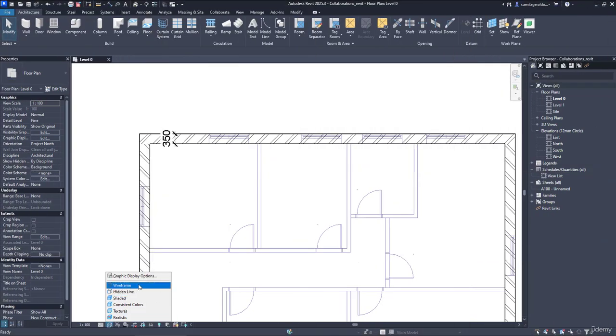Because with that, we can see where the windows and doors are located, so we can model these elements in the right places. Now, I encourage you to continue modeling the remaining elements. First, start with the interior walls by measuring the thickness with a dimension line. Then choose a type, duplicate it, and edit the width. And finally, model the doors and the windows using types that roughly fit with the drawings.